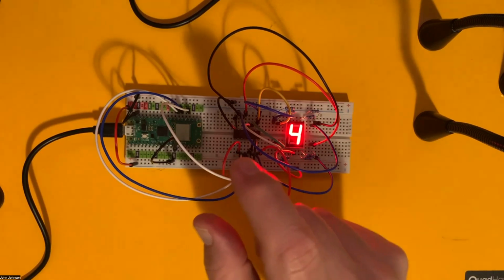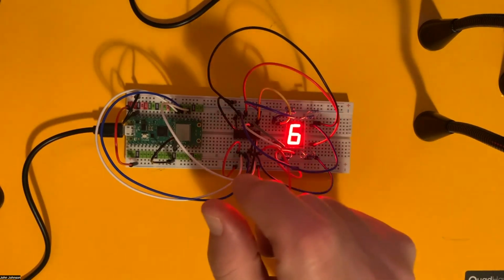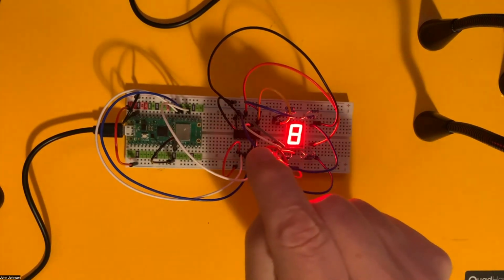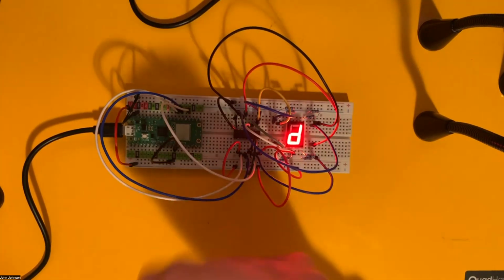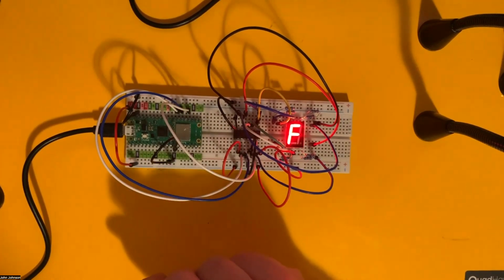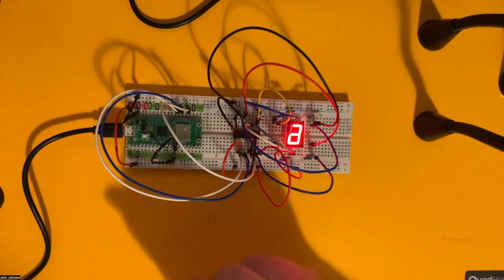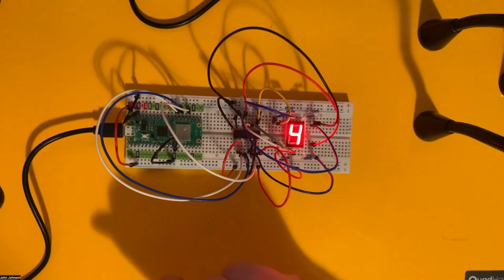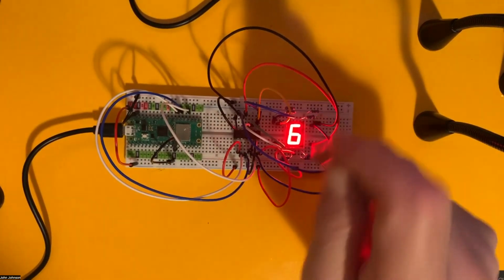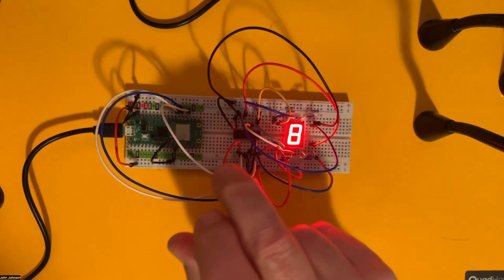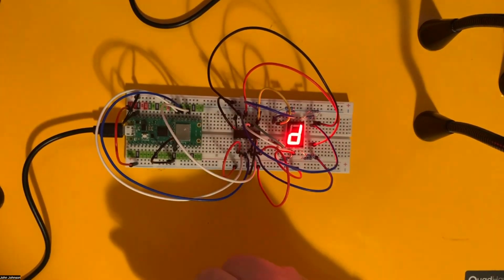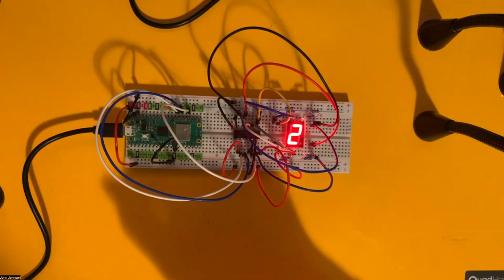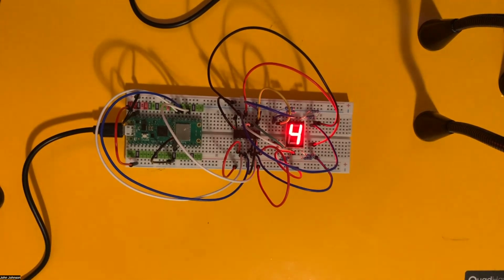That came from when I pulled it out. Maybe one was off a little bit, and when I went to push it back down, it crimped under, just like this. So it wasn't making proper connections. Maybe it did sometimes, maybe it didn't. But that was the problem. So if you have erratic issues, check your chip. First of all, make sure your chip orientation is proper, and then make sure that your legs are not crimped under or bent up. So anyways, that is 15.1.